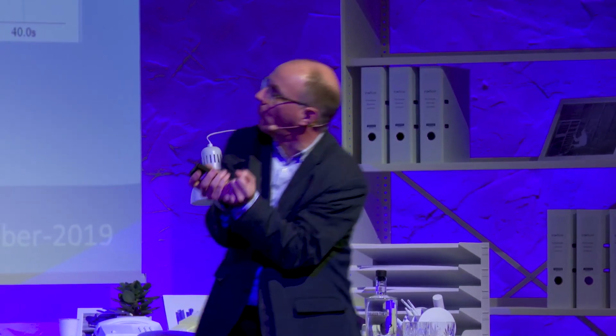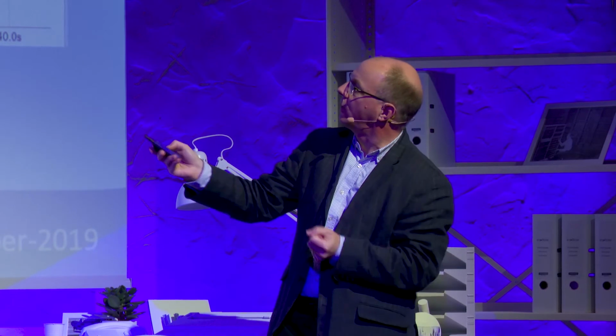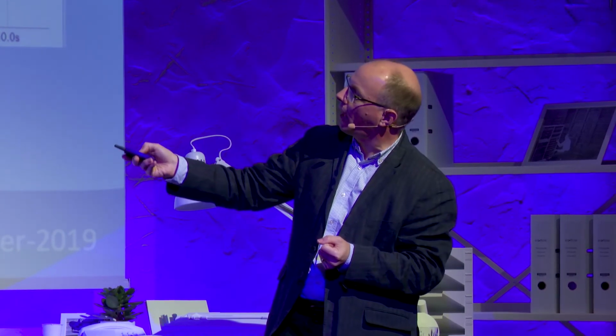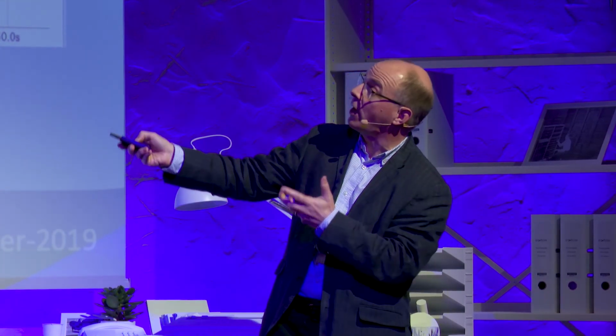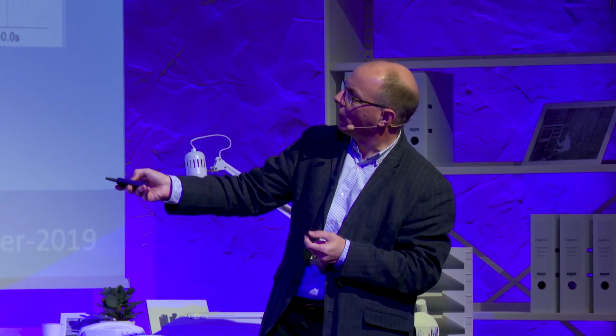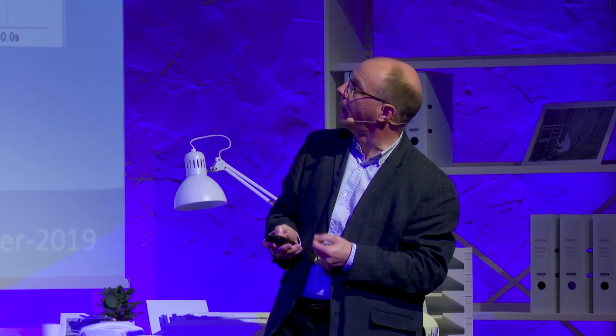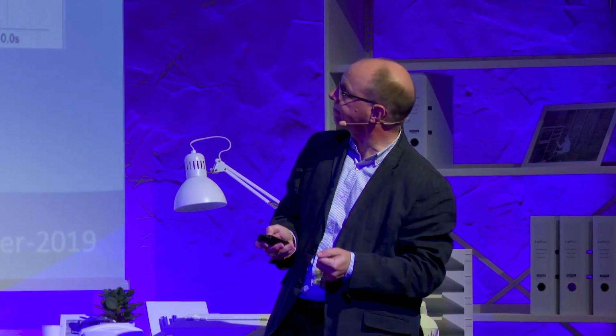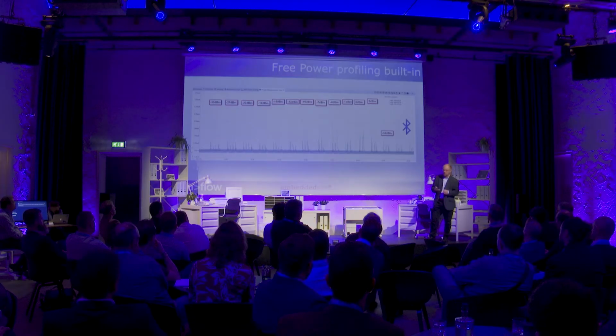With the idea being that when we're pairing and we want to be physically close to the node, we have the part in a low power radio mode, and in that case we saw an average of about 1 milliamp when we were advertising. So tools are available. Your software engineers will probably know about these tools, but it's a really good way to get to grips with what's going on.